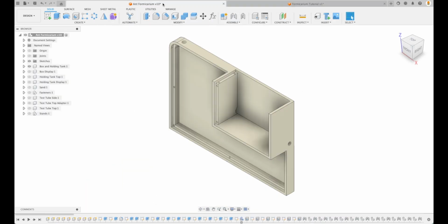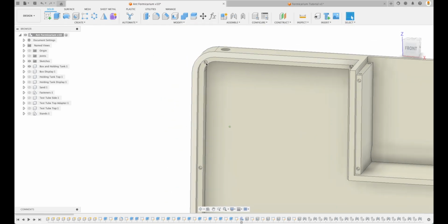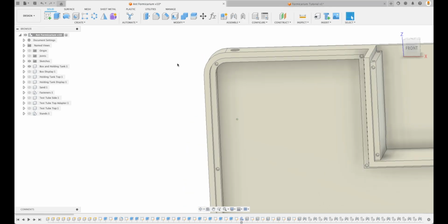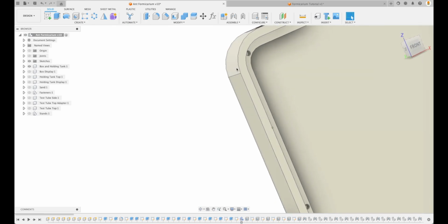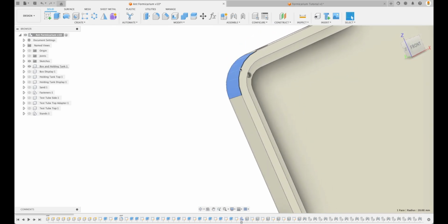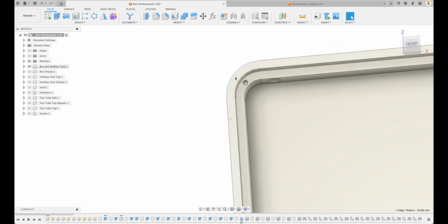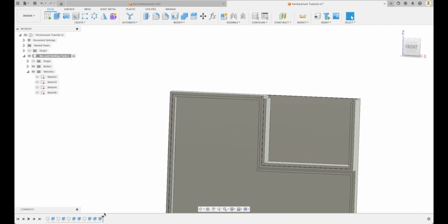If we look at our original file, you can see that we have big loopy fillets over here on the corner. Now, it's probably a whole lot better if we put that on early. And you can see that if we specify this outer fillet first, this is at 20 mils. Well, if we design it right, we don't have to specify these other interior fillets. Fusion will do that automatically for us. So let's do that. We just have to do it at the right time.